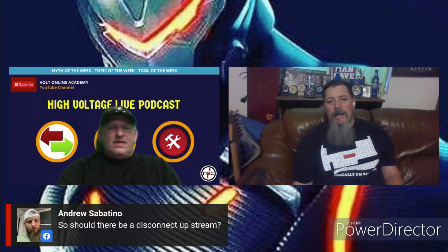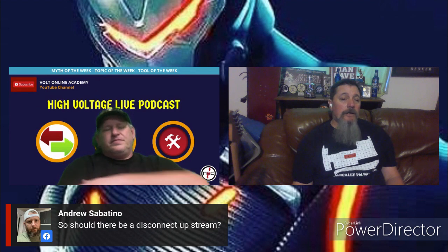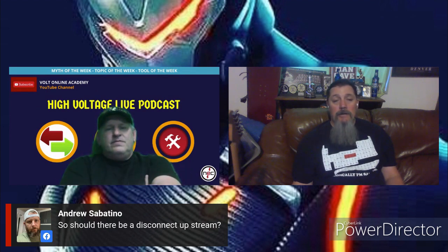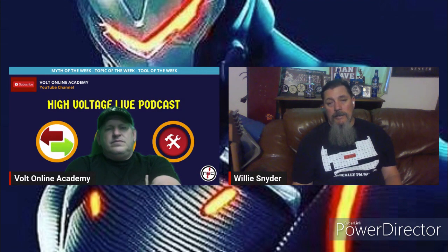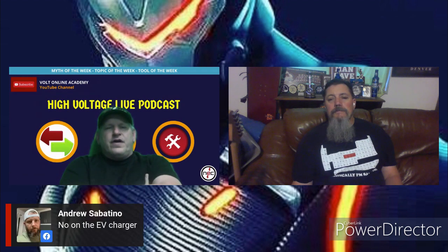Appreciate you, Andrew. And Andrew's asking if there should be a disconnect upstream of the shunt trip breaker behind the oven. I would imagine that it comes off a breaker, and I would actually say the breaker would be sufficient disconnect upstream for a shunt trip. And I'm not sure the exact situation, Andrew, so I could be completely off base. I could be 100% wrong, but that's a disconnecting means. If you go look at the definition of disconnecting means, it'll say a device or group of devices, and if you go look at device, guess what's listed there? An overcurrent device.